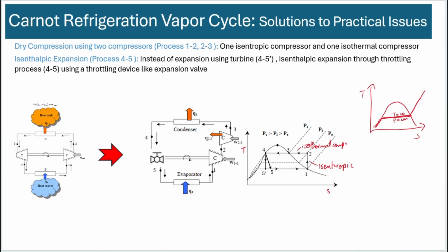And then the temperature increases in the vapor region with pressure, just like an ideal gas. So if you try to compress outside, you'll get to a pressure, but you're not able to turn left without doing an isothermal compression. So you go to another higher pressure, so this P2 is greater than this P1. So you're doing compression in both these cases, okay? One is isothermal and one is isentropic.